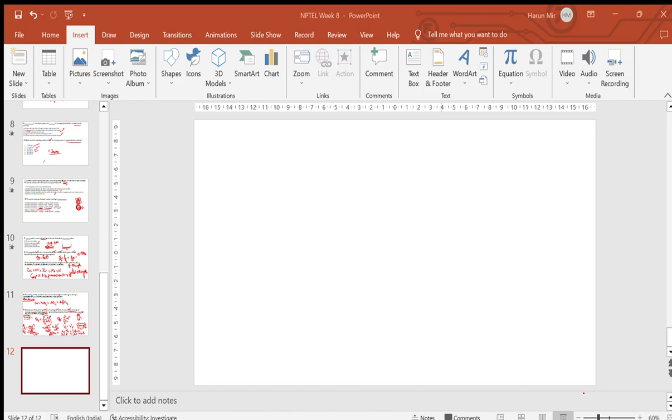So you need to identify, apart from your particle morphologies, particle specific area, their hardness or yield strength, you also have one parameter which is your geometry of the mold, that is affecting your responses, that is affecting your mass flow rate in a mold, right? So this is one of the parameters. So just an example for your understanding to see that there is an effect of your mold geometries on your mass flow rate.